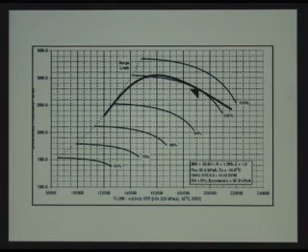The other curve shape we sometimes see is where the flow range isn't quite as wide as we had expected, and it just falls off. Again, if we have a very narrow process change, this would be an acceptable compressor as far as we're concerned. But if you have to be able to go below this flow rate, you actually have no way of getting there, because you would be closing your valve to build up the pressure rise to reduce the flow until you get to this point, and now you actually have to open your valve up to be able to come down on this side if you needed to get down into this flow range.